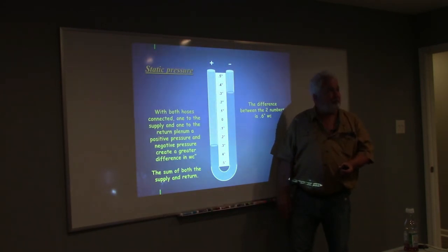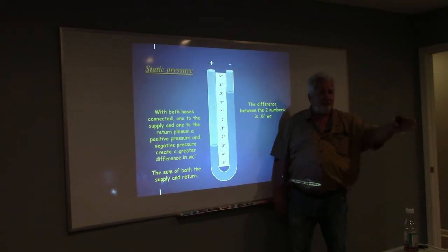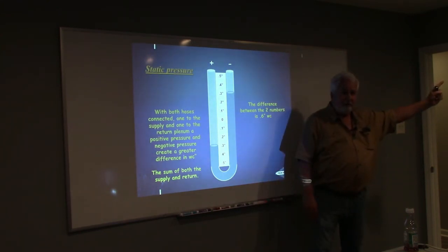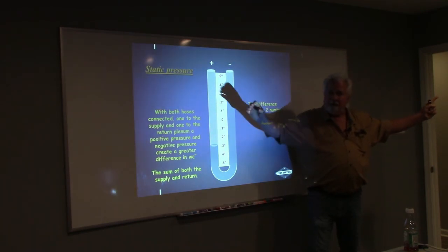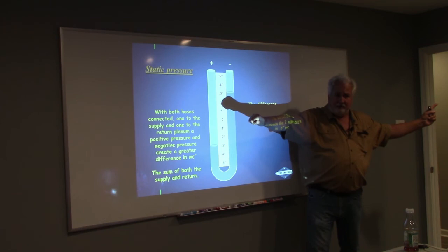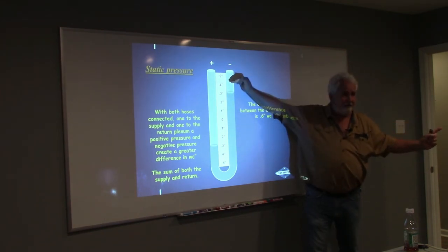Kind of cool. You with me, Dan? Why are you putting such an emphasis on the external? On the external, because everything in that supply was a resistance, wasn't it? The coil was a resistance. Was the ductwork a resistance? Was the grill a resistance? On the return side, if that grill is very restrictive, that blower's going to do what? Resistance is higher with the grill. If that ductwork is small, it's going to pull harder, yes? Higher resistance. It's going to suck it up even higher, yes?